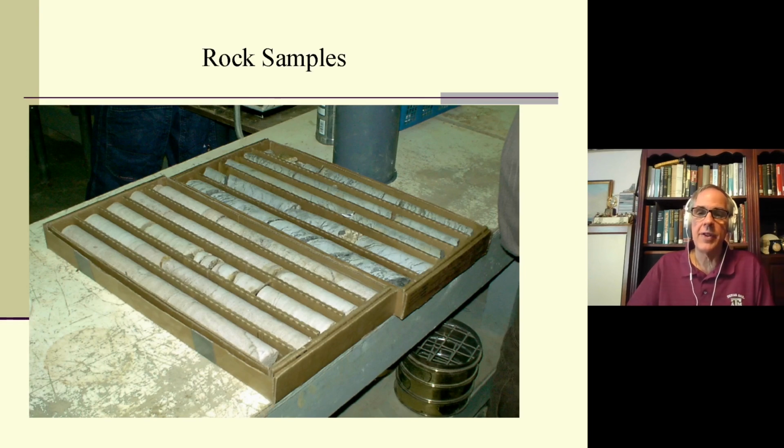Now, how solid that cylindrical shaft of rock is depends upon the integrity of the rock it's taken out of. If it's very solid rock, then it's going to be like the one on the left, which is fairly solid. If it's not, it's going to be more like the ones over on the right. And that distinction is important because the most important single test that we do for rock in terms of the design of structures to go on rock is the RQD, the rock quality designation.